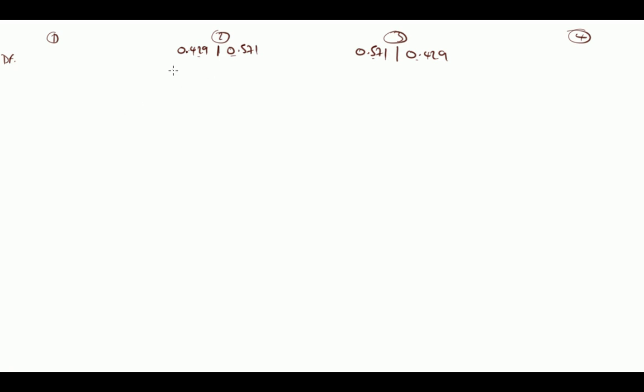So we have our fixed end moments, which we said were 0 at this end, which was a pin, 31.875 ended up at this side of the joint. This is before we release them onto the structure, so these are our fixed end moments for the individual spans, which we have imagined separate.